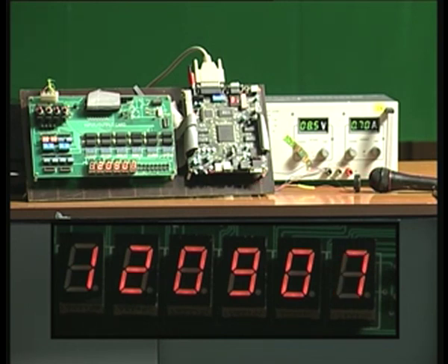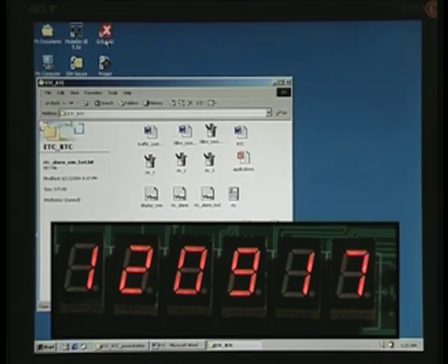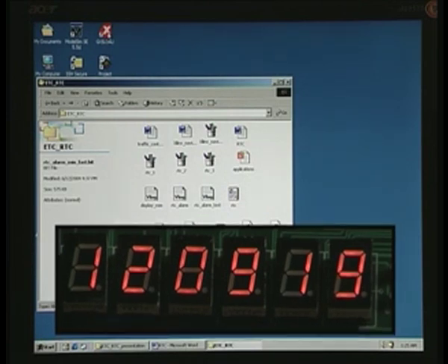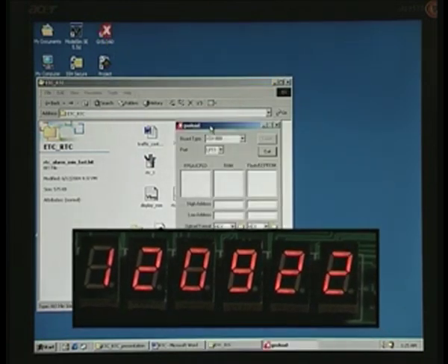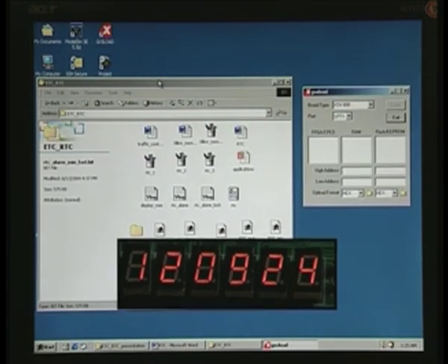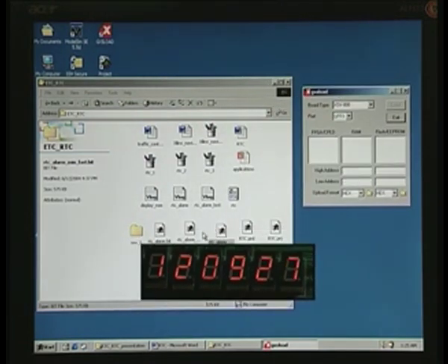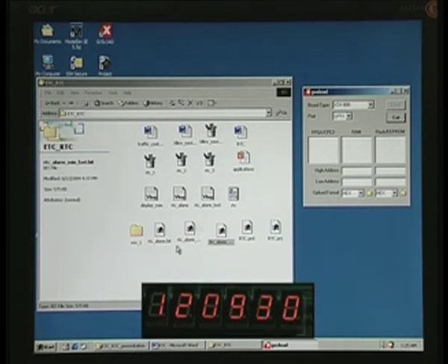And to start with, what we need is a load. So on the system that you see here, there is one GX load. So just click on that one. It opens this window here, and this window has different bit streams available, which is the result of Xilinx place and route. So, this is for the RTC alarm dot bit, and I have also made one hours fast as well as minute fast.